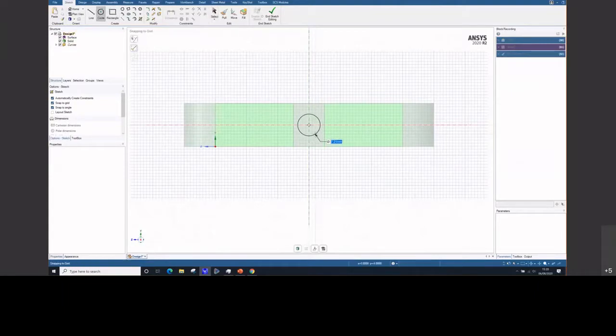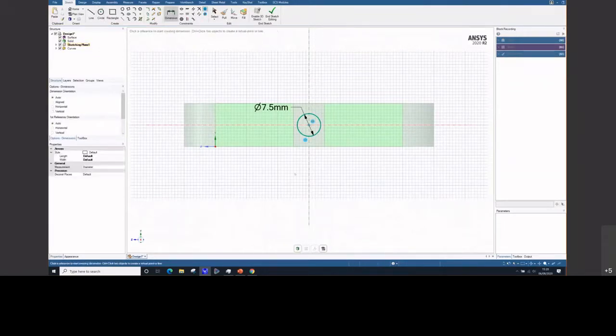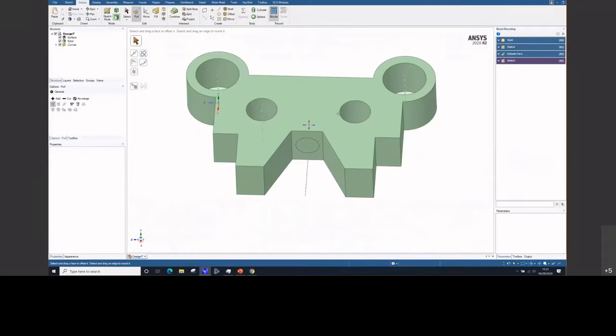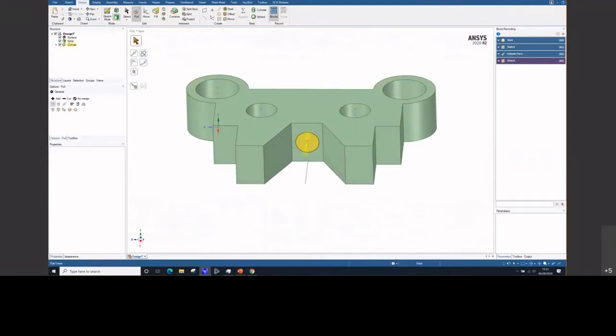and I might have, let's say, a 7.5 mil circle there. If I want to actually modify that circle potentially later on, or potentially a different variation or version of this model has a slightly different hole here, I add my dimension and literally end the sketch editing. We'll see another sketch here, and we can see our dimension appear there, which can be modified there. I'm going to do a simple pull as a cut through that model.